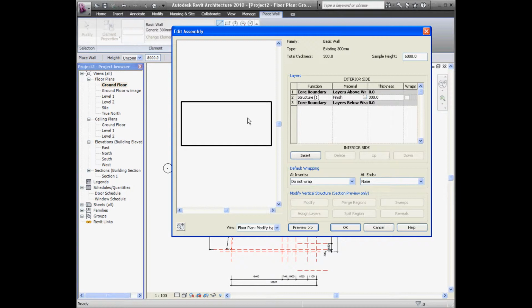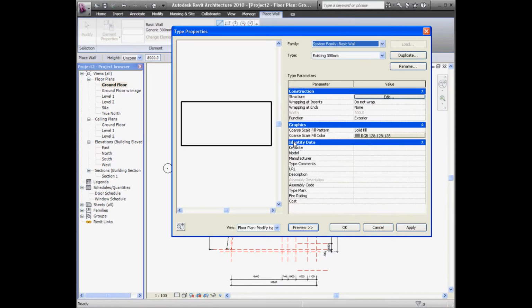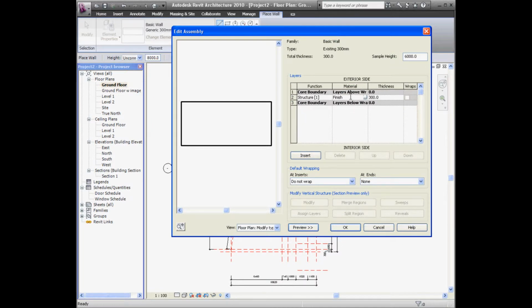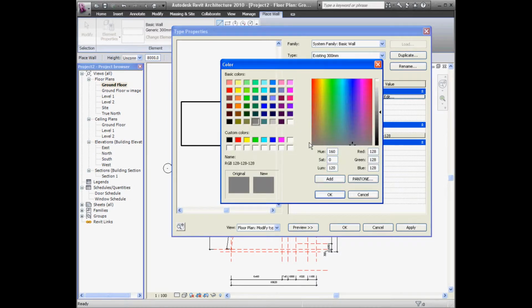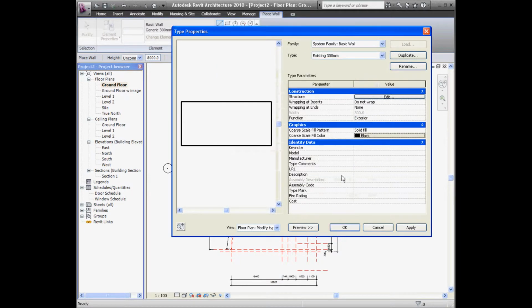But you might have noticed when you go to draw these walls that they'll have a grey solid fill. So I don't know if you've wondered why, but it's all to do with the fact that you have a coarse material as well as the fine and medium material. So they're two separate settings. And so here I can just change this coarse scale fill color to black. And that means as long as I set or leave this view set to coarse, which I'll do, I'll just...